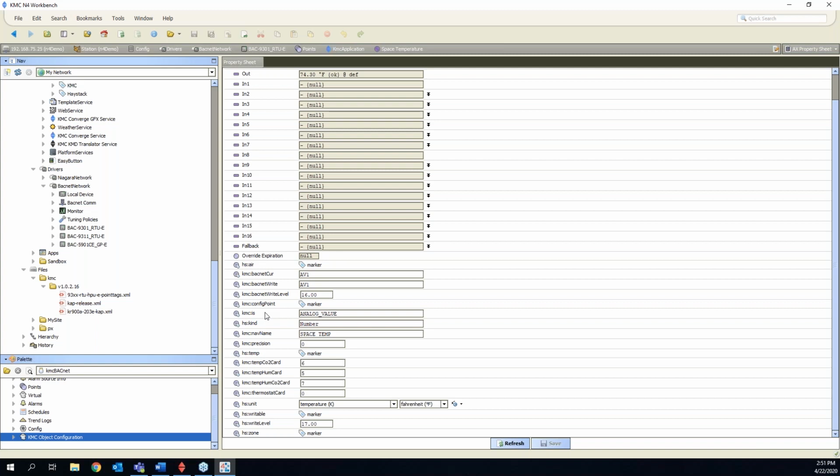All right, so the last question for the whole panel before we wrap it up today is kind of an interesting one. It's a scenario. I've had issues when using a 5051 router in Niagara and getting extremely long BACnet busy times, and this makes my communication very slow. If I put that MSTP segment directly to the Jace, the issue seems to be resolved. Do you have any recommendations on tuning this communication, or what might be the problem here causing slow busy times?